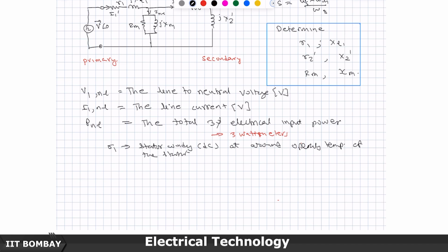So, one way of handling this: skin effect is a very serious issue in power systems, but here in motors what we can do is have parallel small conductors. When you have parallel small conductors, the current distributes in so many parallel strands, and that way you get a much closer value to the DC resistance.